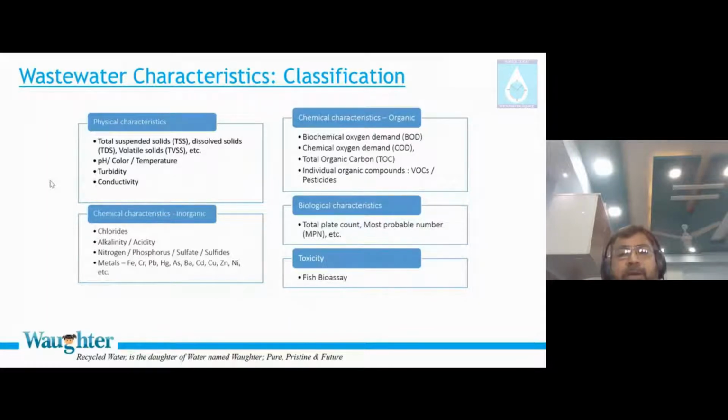And finally, biochemical oxygen demand is a measure of whether, to manage this pollution, I need the help of chemistry or the help of bacteria. If I take the help of bacteria, and bacteria can eat it like food, then that portion of the organics is biodegradable. So for any sample which you get into wastewater treatment, it is important to check its biodegradability. The biochemical oxygen demand is one such test to understand the biodegradability of the waste. BOD is not a pollution. BOD is just a number. COD is the pollution. BOD is only an indication of how much oxygen I'm going to consume if I try to manage this COD using bugs. So I hope that clarified the difference between BOD and COD.